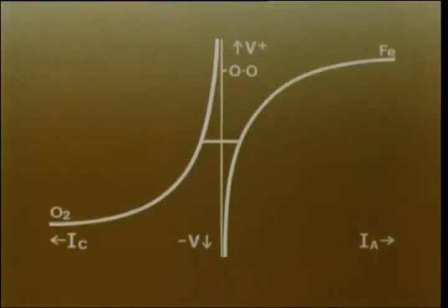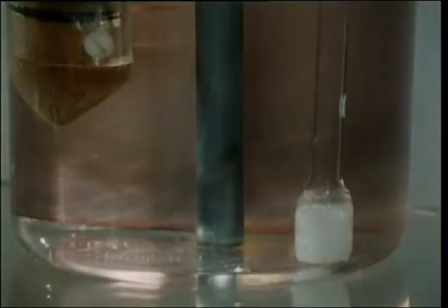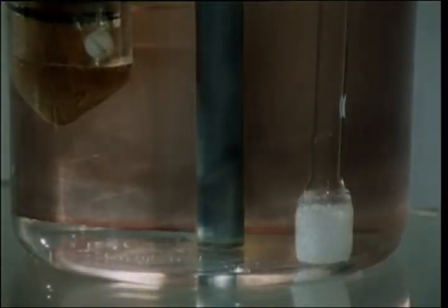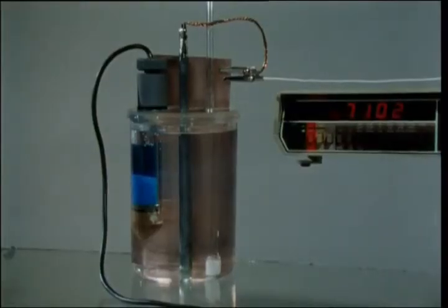Removing air from water will stop steel rusting, because as the concentration of dissolved oxygen is lowered, the rate of the oxygen reduction is also lowered, and so is the corrosion rate, which becomes very low. If air is excluded from tap water, then iron will remain rust-free indefinitely, even though it's connected to copper.